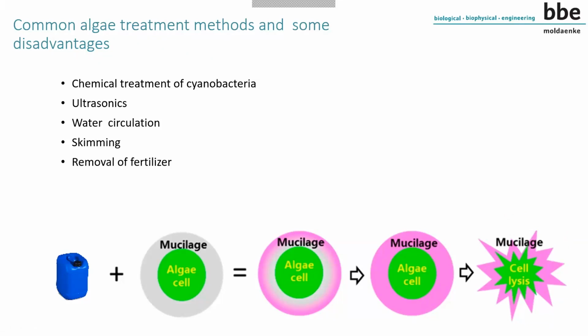Another point is if you use this treatment, let's say also together with ultrasound, which is another way to deal with it, you can destroy them for a while, but is it really effective over time? If you have small ponds, it may be effective. If you have large water bodies, it's very difficult to use. Imagine how much copper sulfate or other chemical you need to use in a large water body.